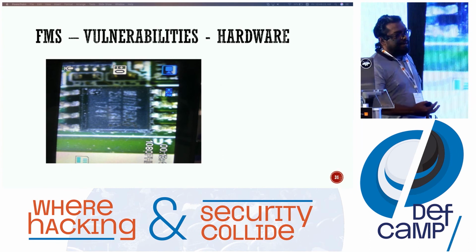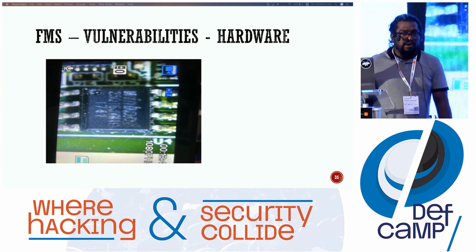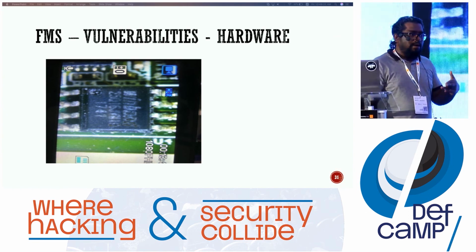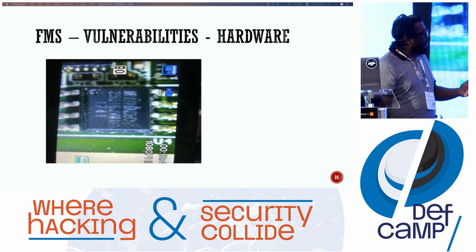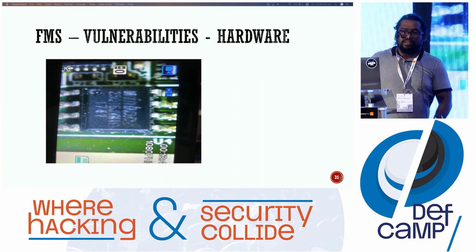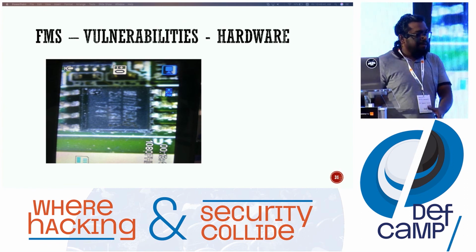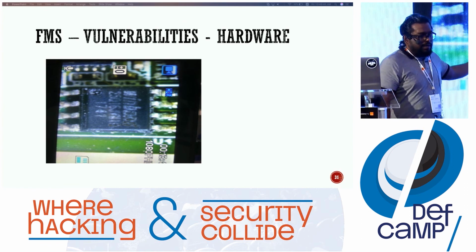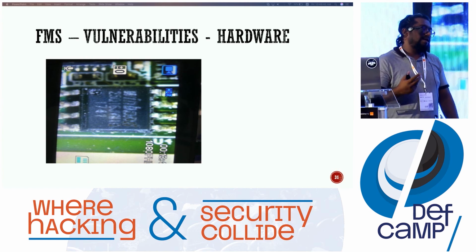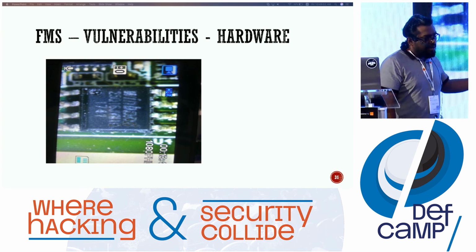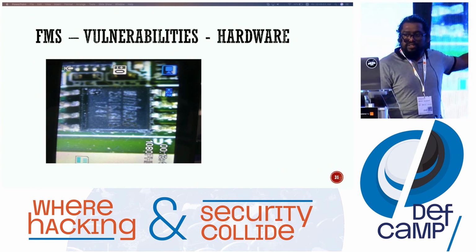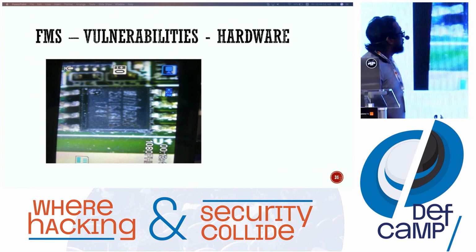We could not find any protocol over the GPS, though I can do some sort of GSM jamming, or I can make a fake GPS, fake BTS, and the fleet management system can connect with my fake BTS, and I can intercept and try to inject some SMS if it supports SMS, or any CAN message through the BTS itself.